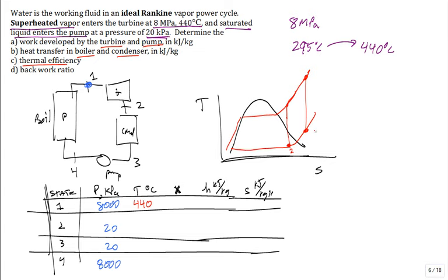Engineers don't want to do that. They would like to get state 2 kind of tucked up into this region right in here. High quality, but we got a lot of energy out of that steam. Some of the water is in the form of droplets. Okay? But theoretically, if you way superheated it, go state 1 way out here, state 2 could be superheated